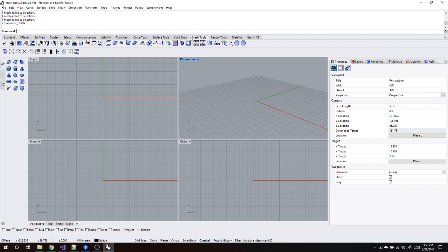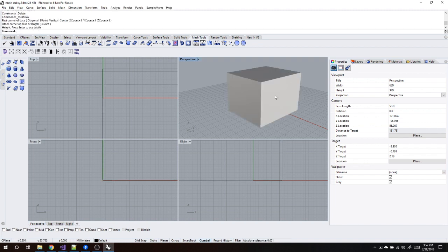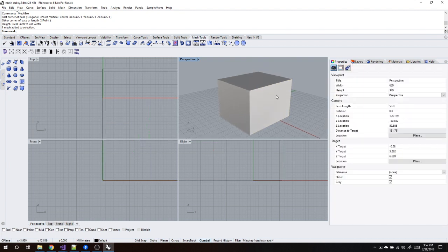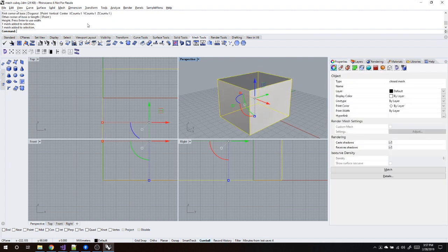I find the easiest place to start is in the Mesh Tools tab within Rhino, and then the box type on the left, or mesh box type more specifically. So I'm going to click that, and then I'm going to click 2 times to create a 3D mesh box type. The important thing to keep in mind here is that the mesh box has an X count, Y count, and Z count of 1 in the source properties, and that the type of your mesh can really be any closed mesh, though I find that meshes created out of quad surfaces that are low poly count usually work best.